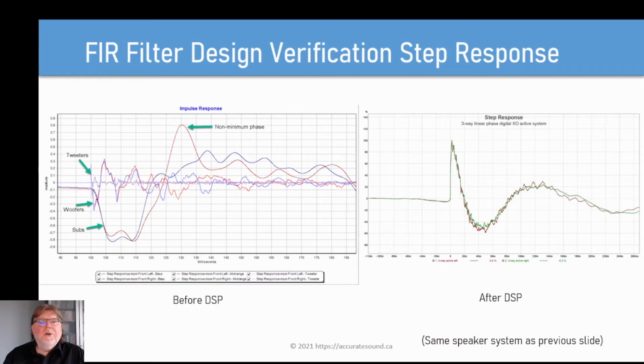I think it's important to reiterate that it's possible to hear differences between transfer functions, one being time domain corrected and the other not, for example. Hang Loose Convolver makes it easy to A/B and even ABX test the differences, as the filters are level matched and switching between the filters is instantaneous. There is limited research here, as I doubt any of the preceding tests were done using high-resolution FIR filters. And other than Hang Loose Convolver, there is no easy way to conduct a valid A/B or ABX test using FIR filters with excess phase correction.